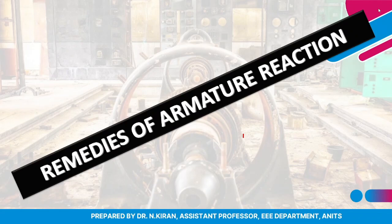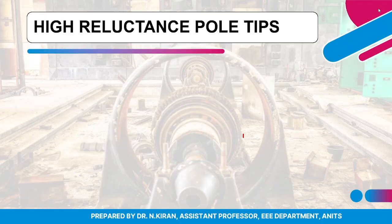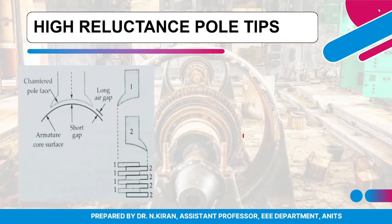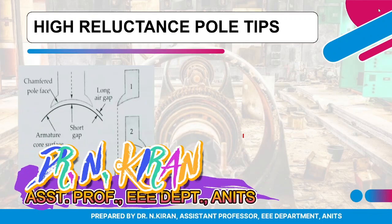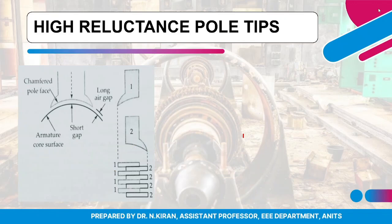So let us see what remedies we have for armature reaction. The first remedy is using high reluctance pole tips. A chamfered pole face is used, so the air gap will be short exactly in the midway, and near the edges the air gap will be long.